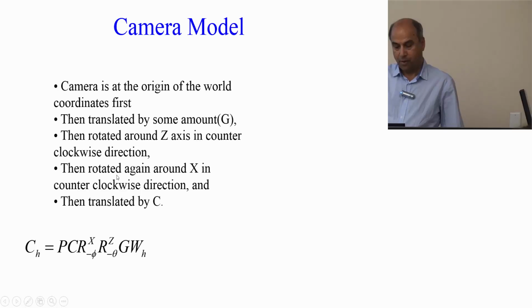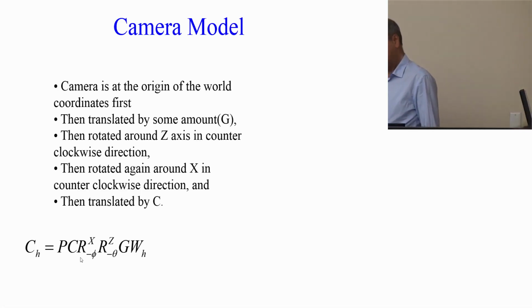There is the rotation on the X-axis, which is this one. Then another translation. Then we take a picture, which is the perspective transformation, the P. And these will be the image coordinates in a homogeneous system. So all these things we have to keep in account to relate the pixel coordinates with the actual world coordinates in 3D.